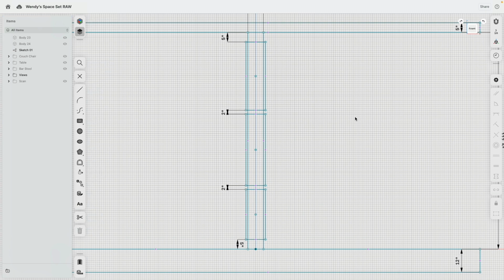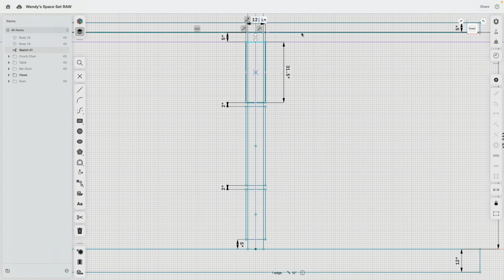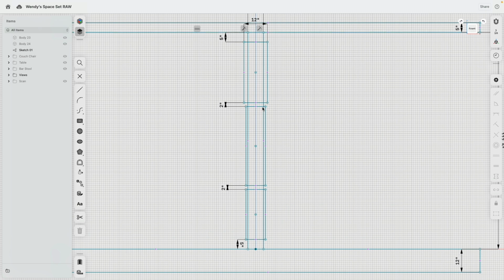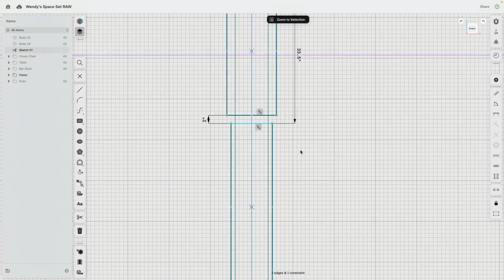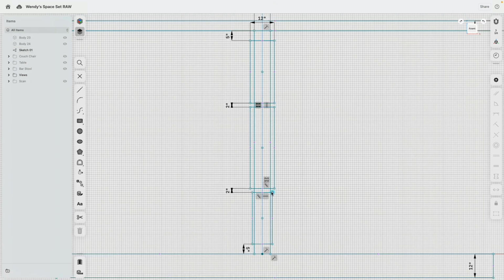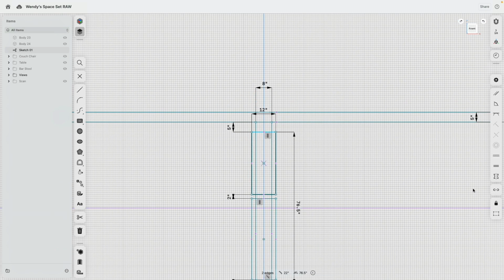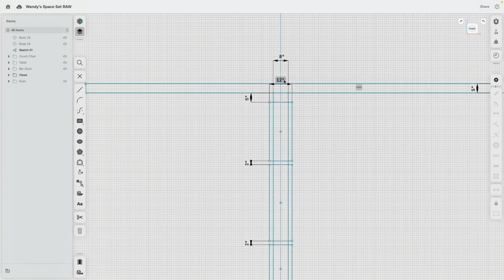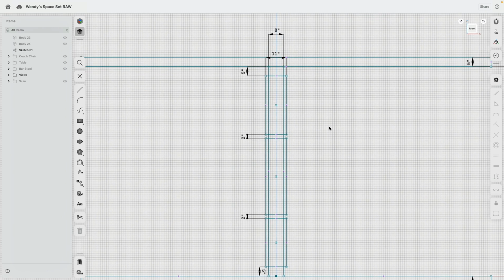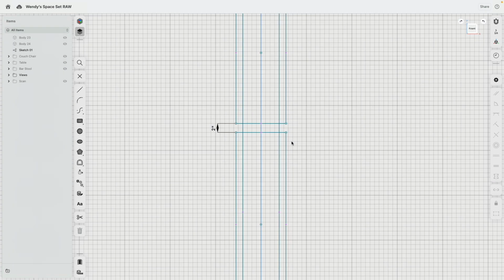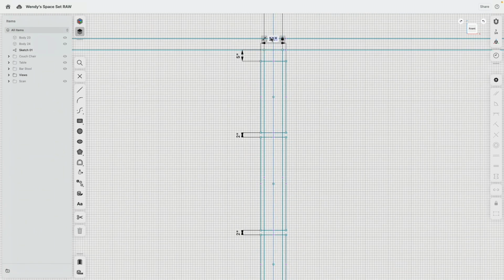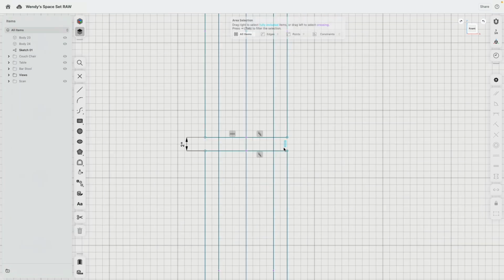Well, there you see this already. It's actually pretty easy. And that should be, what about we make this 12? Yeah, let's make this 12. Then we can say all these upper edges, I make all equal. So I only have to do this one time. Very good. If I make this 11, you see how this shrinks quite nicely. Pretty cool. Okay. I will go with 12 because then I have a nice squarish gap here. So the height is also the width.